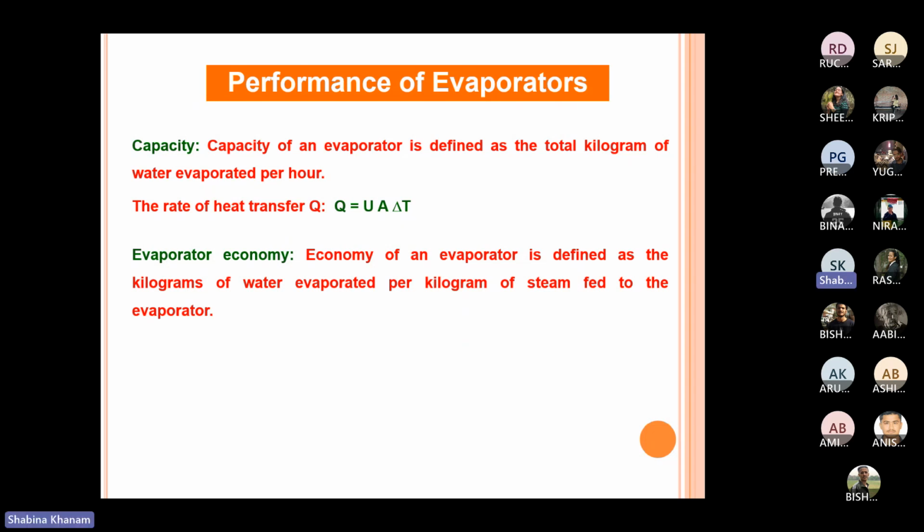In that way we consider the evaporation, which is known as a multiple effect evaporator. Let's say if I have three different effects, the economy would be 0.8 into 3. So 0.8 times the number of effects would be the economy, which we consider a reasonable, or good, economy.